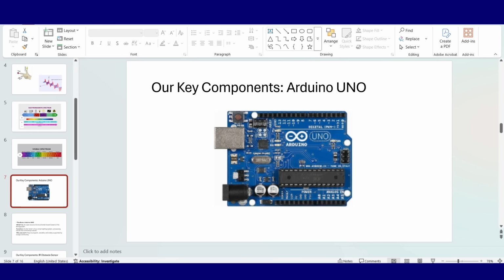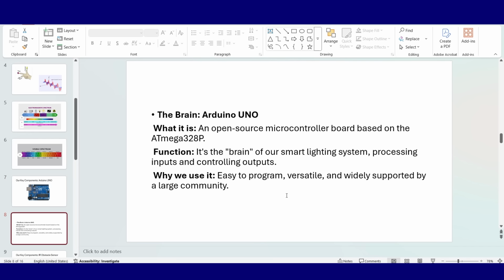It is the most popular 8-bit AVR microcontroller board, which has around 14 pins which are digital or analog pins. It has 32 kilobytes of flash memory, 2 kilobytes of SRAM, and 1 kilobyte of EEPROM. It clocks at a frequency of 16 megahertz and it can reach up to 20 megahertz also. It has a lot of features like UART, SPI, I2C, timers. If you want more information about the Arduino UNO board, please download the data sheet from the Arduino UNO website.